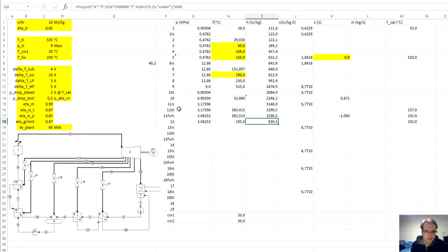So same principle as we did for the first bleeding stream will also take place for the second one. So state 13 at feedwater heating inlet, we want temperature 190 degrees C, which is the required outlet temperature at 0.7 plus minimum temperature difference 5.